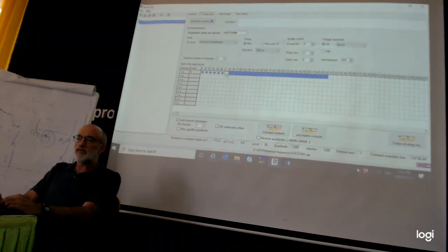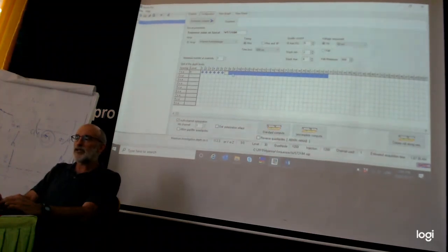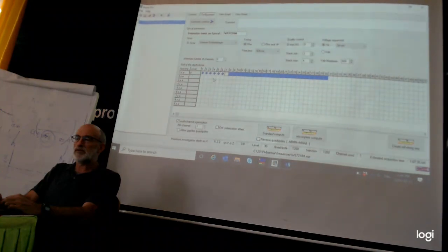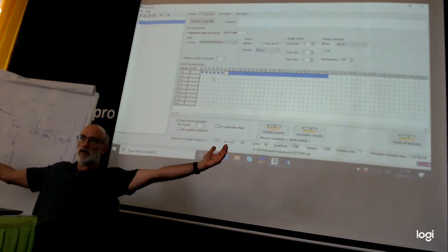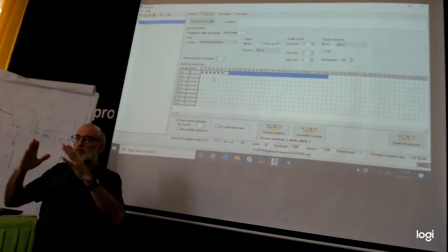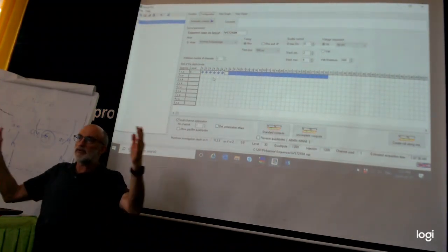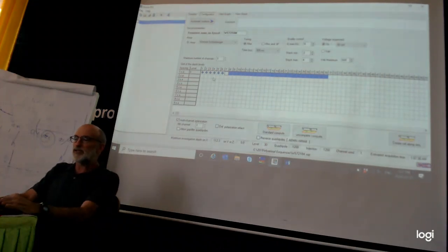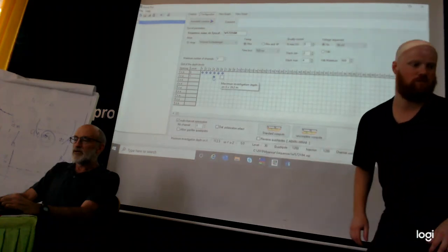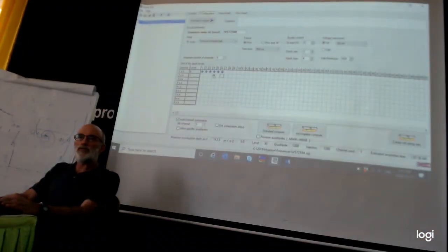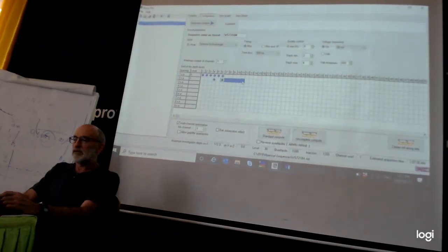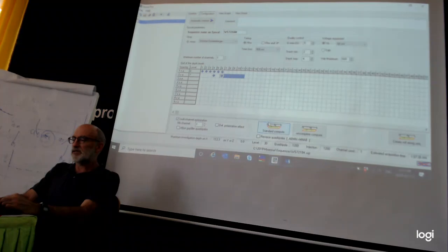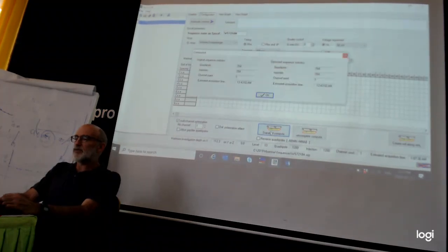So for a dipole, you'd usually just use 6. For a Wenner Schlumberger, you can use 8, but we want to try to expand our AB electrodes and our MN. So we generally just do 6. Overlap 1 right here, and then turn on another 6, and let's see what that gives us.